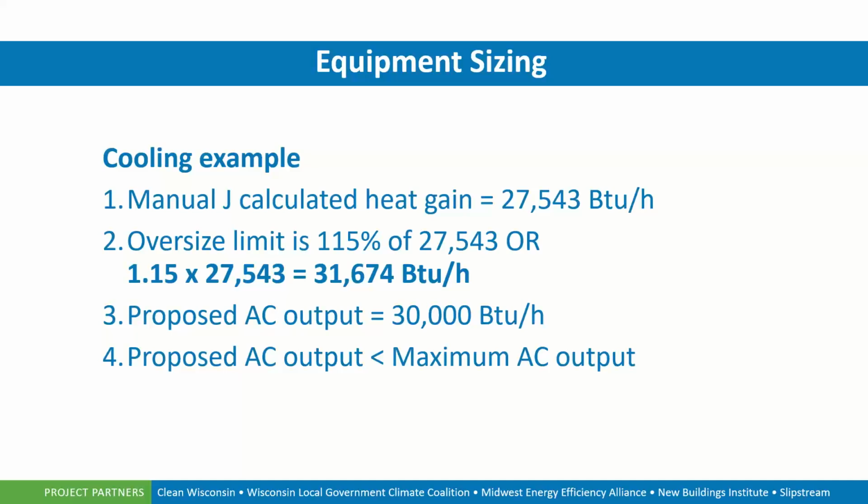When we look into some of the information for cooling equipment, you may see sensible and latent heat. We mentioned that earlier, sensible capacity versus latent capacity. Sensible heat is felt or measured by a thermometer. That changes the temperature of an item without changing its phase, meaning we increase the temperature of an item without, say, changing water to steam or ice to water.